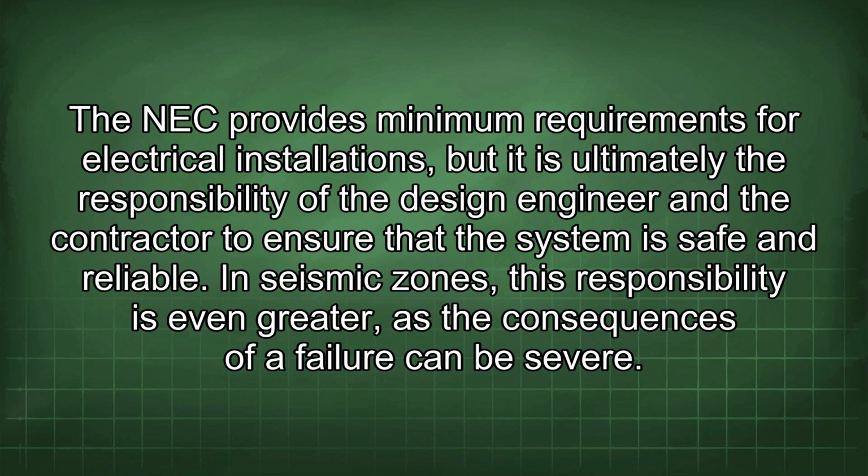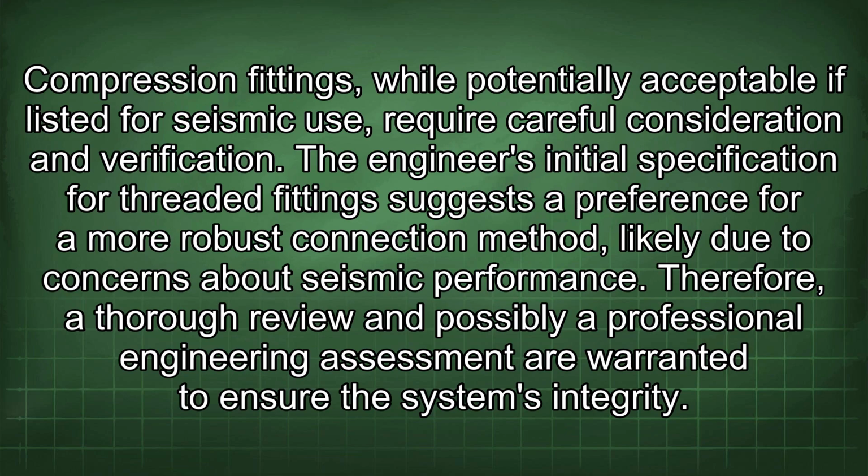The NEC provides minimum requirements for electrical installations, but it is ultimately the responsibility of the design engineer and the contractor to ensure that the system is safe and reliable. In seismic zones, this responsibility is even greater, as the consequences of a failure can be severe. Compression fittings, while potentially acceptable if listed for seismic use, require careful consideration and verification. The engineer's initial specification for threaded fittings suggests a preference for a more robust connection method, likely due to concerns about seismic performance. Therefore, a thorough review and possibly a professional engineering assessment are warranted to ensure the system's integrity.